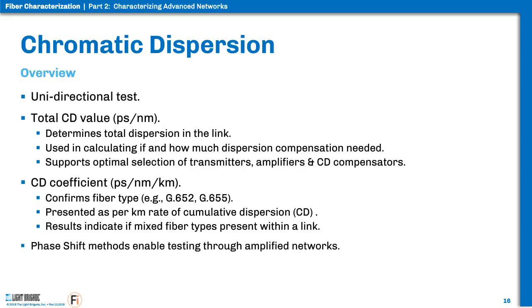The other thing about the phase shift method, there are several phase shift methods, but the phase shift type methods not only enable you to test spans, but they also allow you to test through amplified networks, because you can even use these for ultra long haul or even subsea networks. You can use phase shift methods for that.